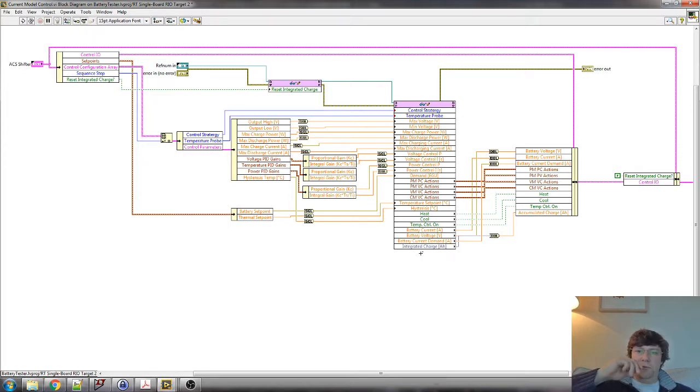I tried to do it before in real time, and then I tried to do it when I was post-processing, and I didn't like any of it. So it's on the FPGA, which is a bit of a shame because you have to do some divisions and it takes up quite a lot of space on the FPGA's resources, but it's by far the best way that I've found. So that's how we get from what the user enters in files and configs into the data that actually comes and goes from the FPGA.